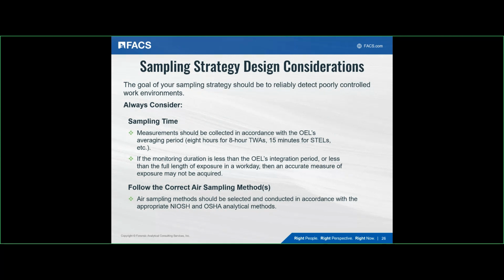Sampling time, right? Making sure that your measurements are collected in accordance with the OEL's averaging period. More often than not, that's an 8-hour time-weighted average. There are shorter duration periods that can be required to assess compliance to short-term exposure limits or STELs, 15-minute increments. If your monitoring duration is less than the required integration period or less than the full length of exposure in a workday, then your accuracy may not be so good when you are deeming these exposures to be acceptable or not.